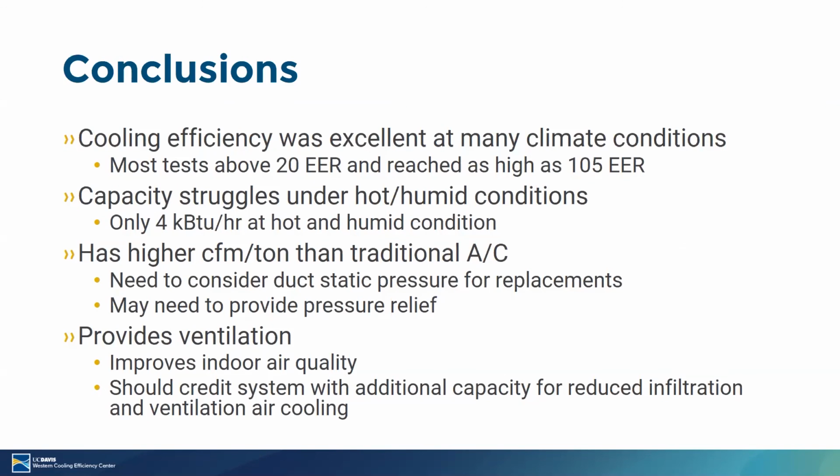Anyway, so conclusions. Cooling efficiency was excellent at many climate conditions. Most tests were between 20 EER and as high as 105. Capacity does struggle under hot, humid conditions, which you would expect. And this technology is designed for dry climates.